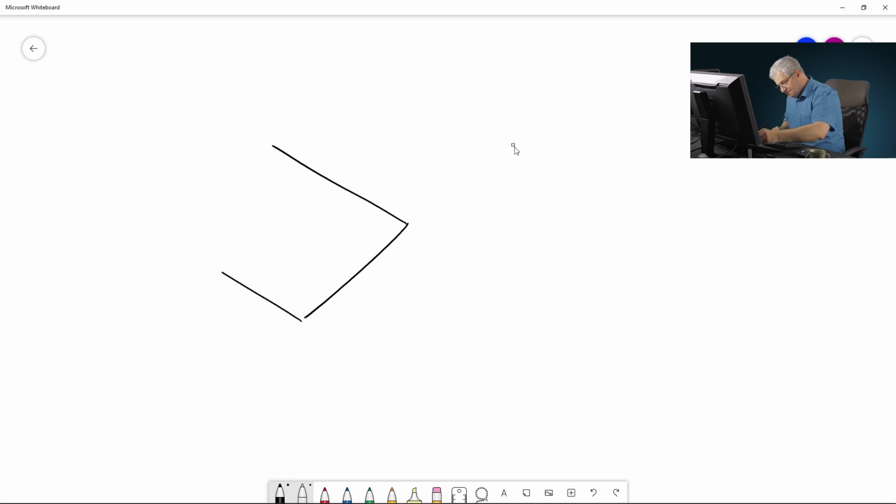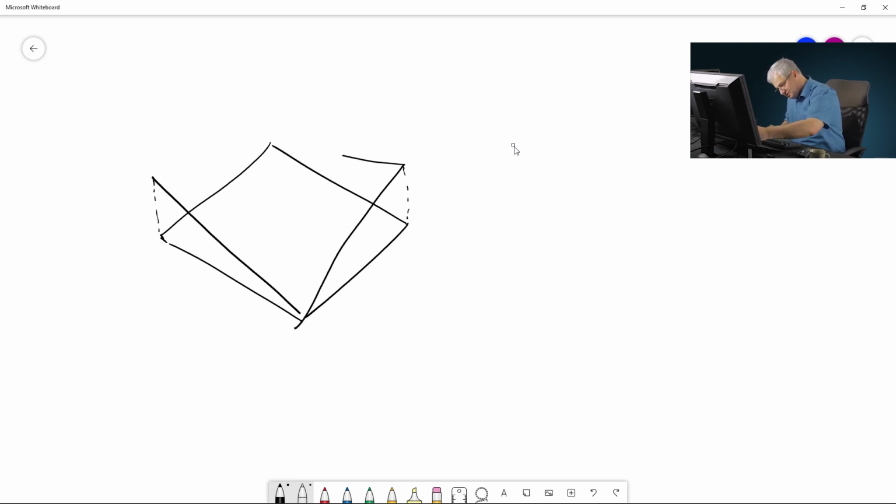So first, this is the ground zero, and for example, I move this corner to the top. So we will add. We have 4 lines. This one, this one, this one, and this one. Line number 1, 2, 3, and 4. What is SCIA Engineer doing? SCIA Engineer transforms line 1 to line 3 and vice versa. And also it transforms 2 on 4. Because we have only straight lines, we still get after this transformation straight lines. So it's very simple.